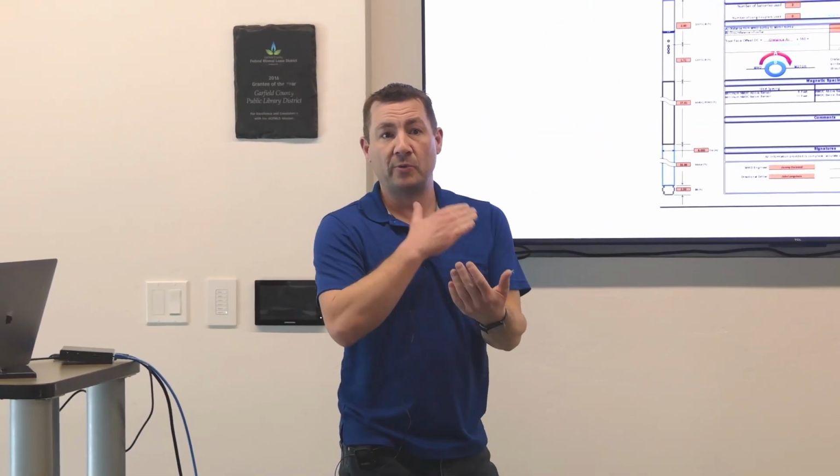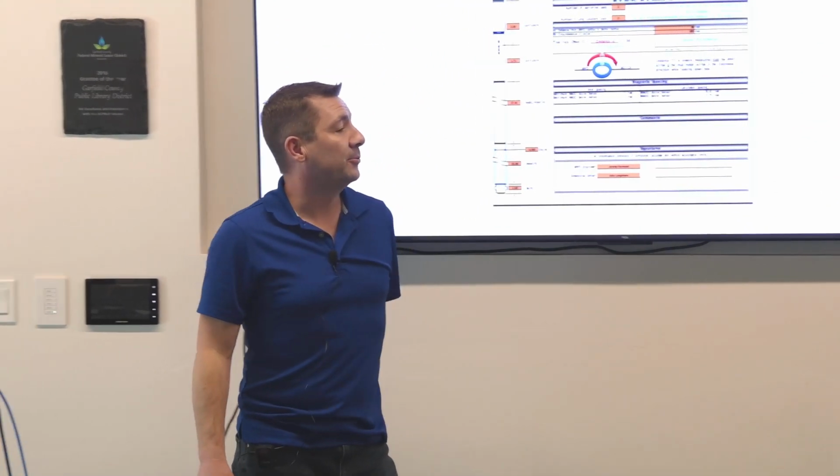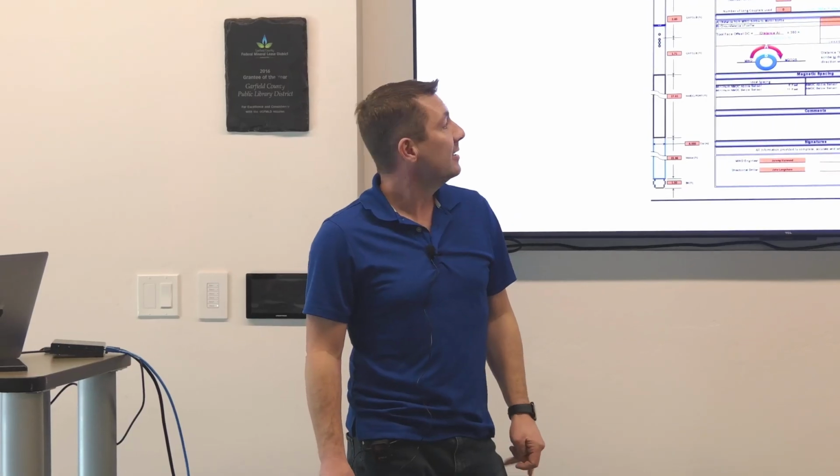So we know where the survey point is taken. We have to have that by law. So we can only take so many surveys. We're supposed to take a certain amount of surveys in a certain amount of depth that we drill. In this case, we have to keep track of where the gamma is being received, so we can give the data to the client of exactly what the gamma rays are in which part of the well.